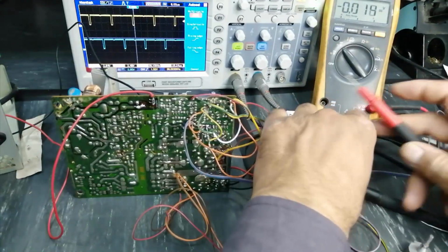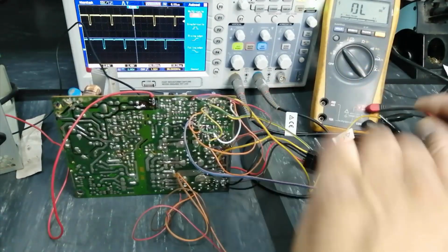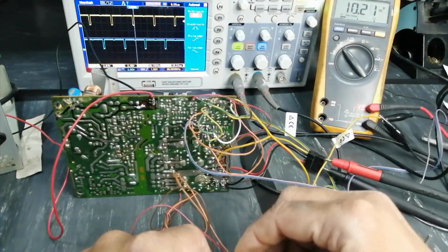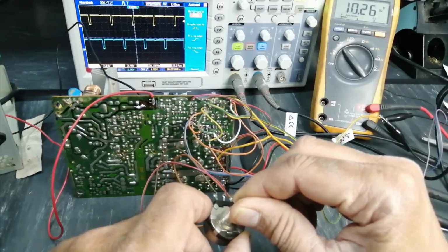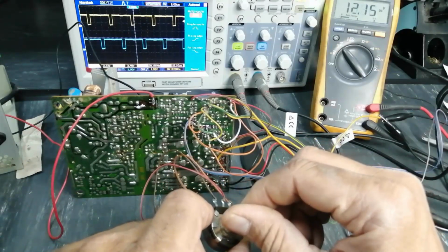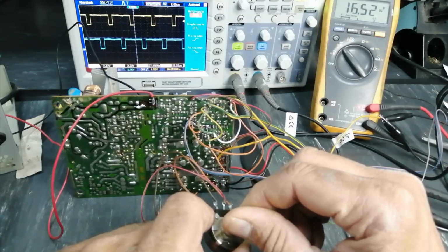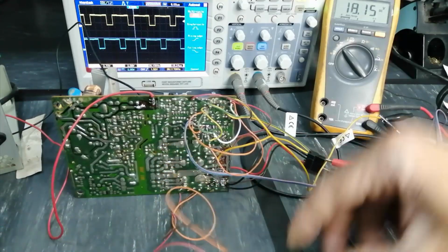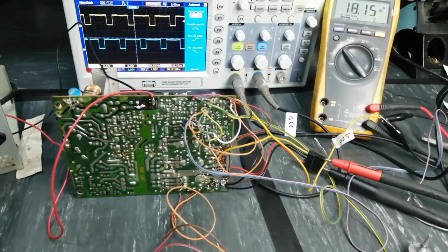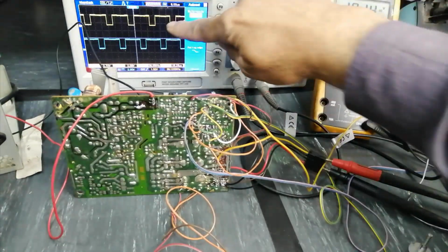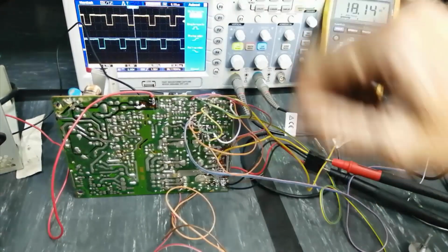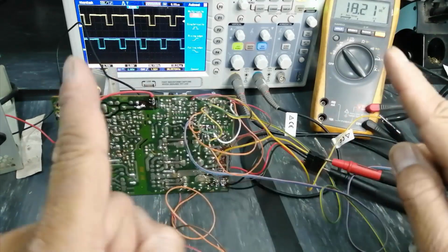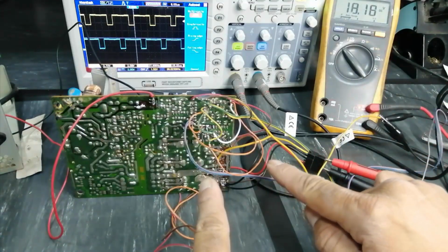So in that case I will take output 10 volt, 0.3 10 volt. Now I will increase more, 12 volt, 15, 16. I will adjust up to 17, 18 volts. We can see the pulse width. This time it is switching approximately 60%. If I allow it to switch at full rate, at that time I will take more output.